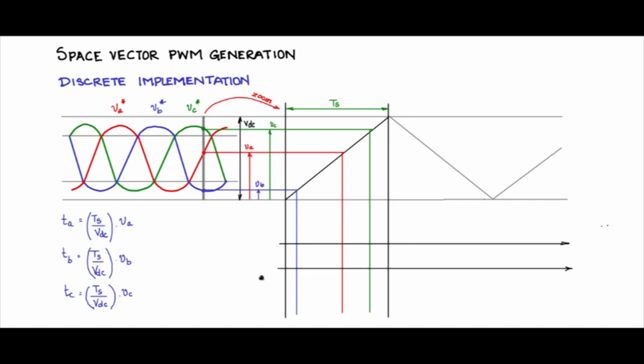Now let me draw the time axis signals here, A, B, C, which are supposed to be the output of the PWM. Now this is a compare thing, this is comparing with some kind of a counter. This ramp triangle is nothing but a timer going up and down, an up-down counter. So anything below that, let us make that high, anything above that is low. So let us say VB is the lowest, this one. So it will be high here and low elsewhere.